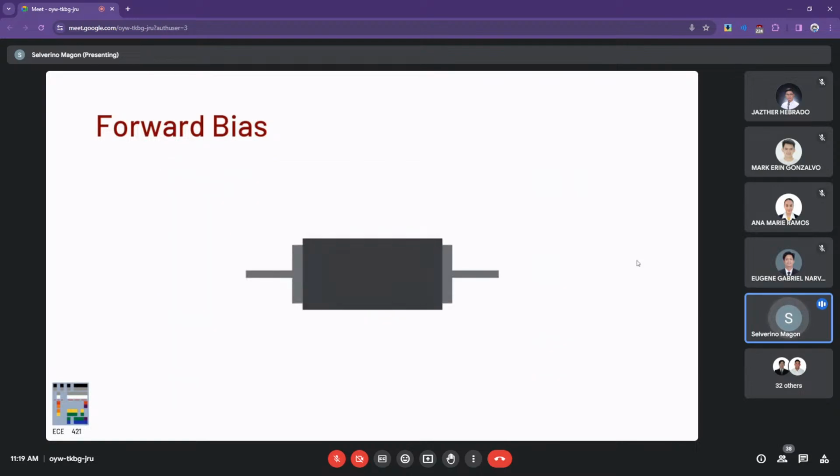A semiconductor diode is a two-terminal device in which half of it is doped as a p region and the other half is doped as an n region. Between the p and n regions are the p-n junction and the depletion region. The p region is called the anode, while the n region is called the cathode, and each of them is connected to a conductive terminal.